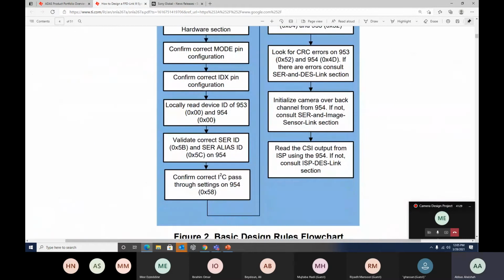So just going back here. From a software perspective, is this clear, or do you want more in depth about it? Local read on both sides, from the imager board to the serializer, and then over the link, and then to the deserializer. Ensure that you match all of your addresses, right? Because if one address is not matched with the other, then you're thinking, okay, I have an issue when it's actually the input and the output.